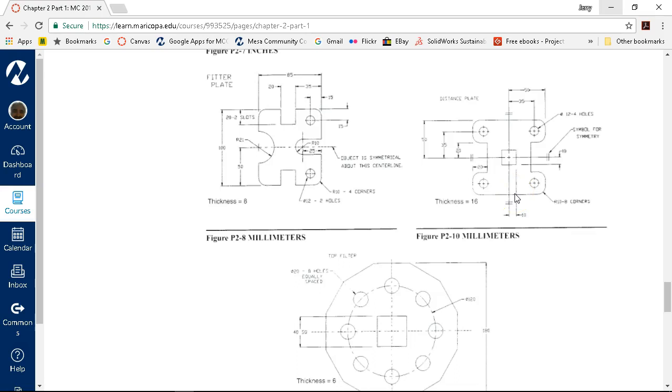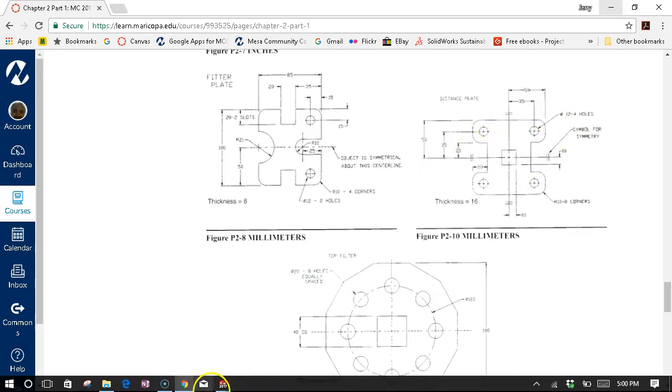And I will pretty much say horizontal and vertical over X and Y because the reference triad gives you an orientation in X and Y. But if you're drawing in Y and Z, are we going to talk about the Y and Z axis or the X and Z axis? Horizontal is normal to your sketch, normal to your geometry, and it goes right back to those relations. So very rarely will you hear me refer to X and Y axes. So the horizontal axis and the vertical axis are both symmetry. So that means that I can draw one corner, mirror across, and have my shape.